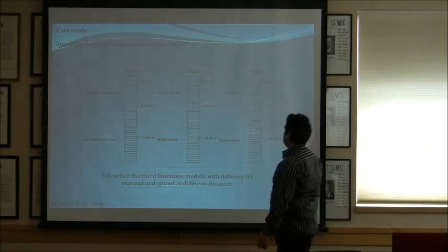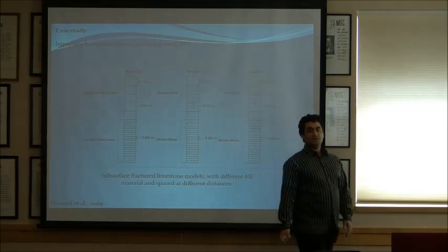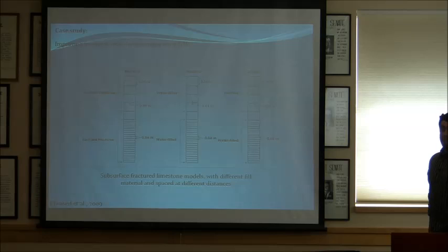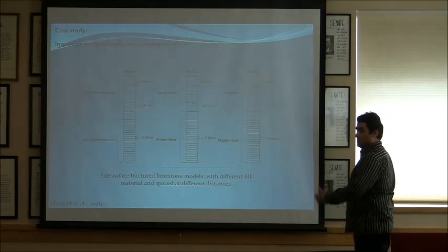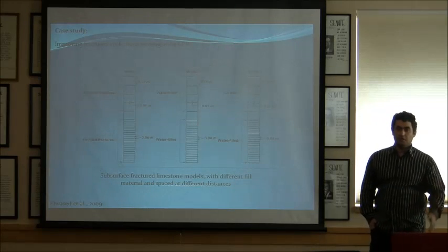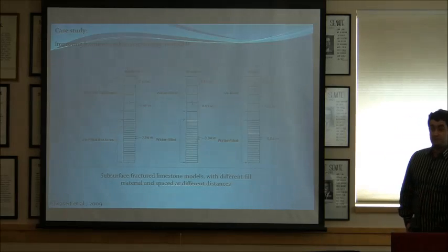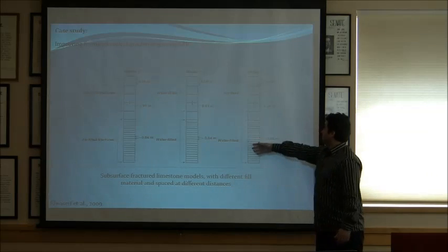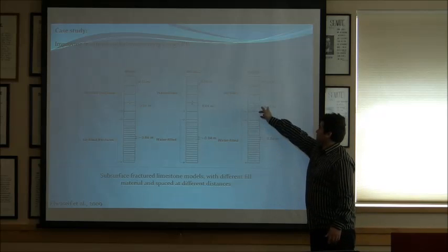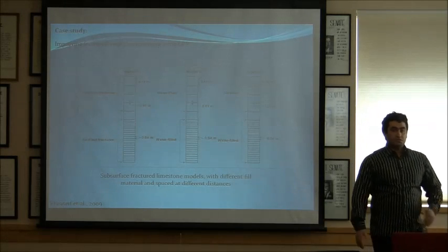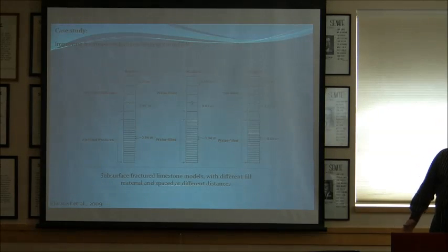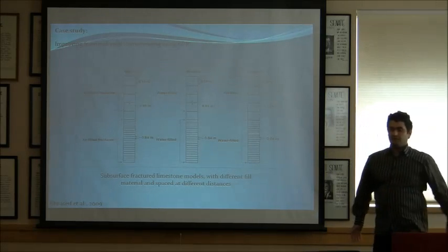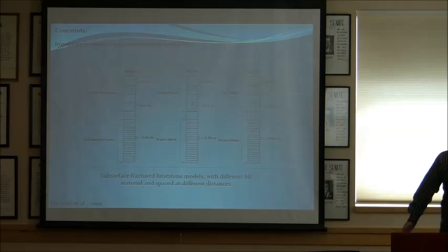Here, in our simulation, we try to simulate fractures that are below the resolution limit of the GPR, or in other words, below a quarter of the wavelength of the transmitted GPR signal. So for example, this is 1 centimeter. It's easier to predict if it is fairly wide, but we'll try to make it harder.